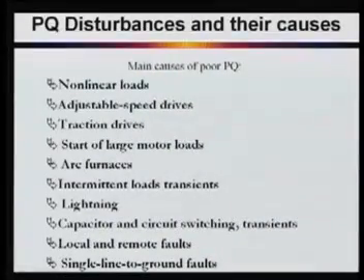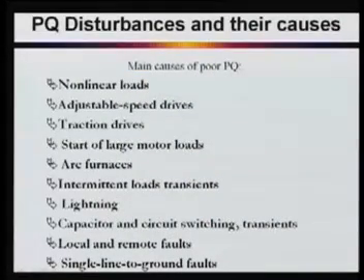Capacitor and circuit switching transients. Capacitors are normally in the distribution system. If you are switching them, the switching instant is very important, and you don't know at which instant you are going to switch. Because they store energy, and we have inductors in the circuit, there may be RLC resonance and other things. So the switching of your capacitor and the circuit, if a line is switched in and out, will create some power quality disturbances, and they normally lead to transients.